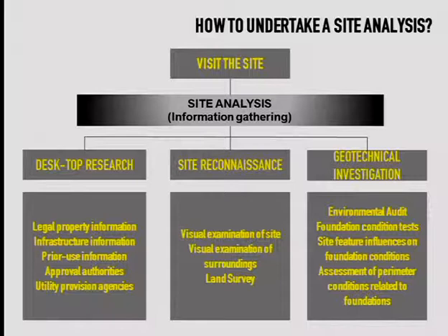Okay? After you've gone to the site, you get a feel for what it is, you've looked around it, you try to do everything that you can remotely. You do desktop research. Okay? So you try to find out any legal property information. Is there any infrastructure information? What about where all the services are? Can I just sit on the computer and try to find that information out?